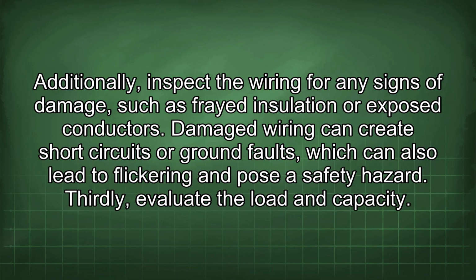Additionally, inspect the wiring for any signs of damage, such as frayed insulation or exposed conductors. Damaged wiring can create short circuits or ground faults, which can also lead to flickering and pose a safety hazard. Thirdly, evaluate the load and capacity.